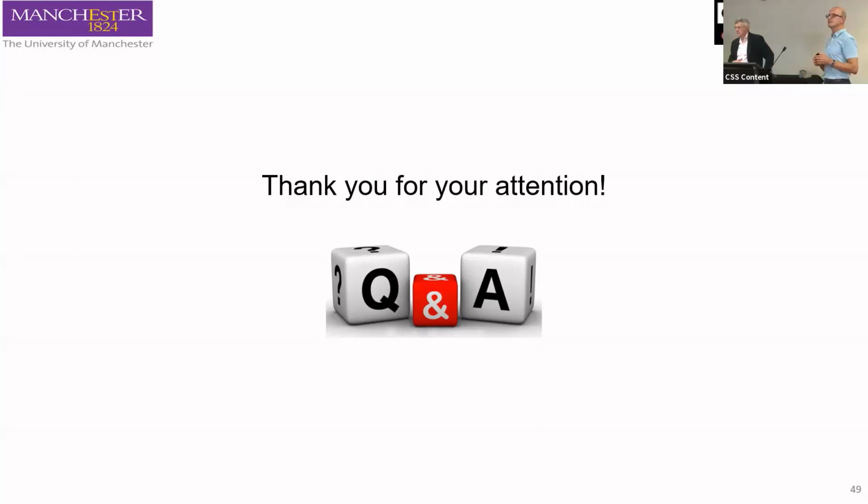Thanks. Hi, Fabio. Thanks very much. I was just interested in terms of obviously the near surface deformed layer brings a different property at the surface, and you explained how that actually helped create a protective oxide because of the effect of the dislocation movement in the creep. But there's also lots more grain boundaries in the very fine structure. So it must be that the transport of carbon with dislocations is a much stronger effect than transport through the grain boundaries, of which there's lots more in the near surface layer.